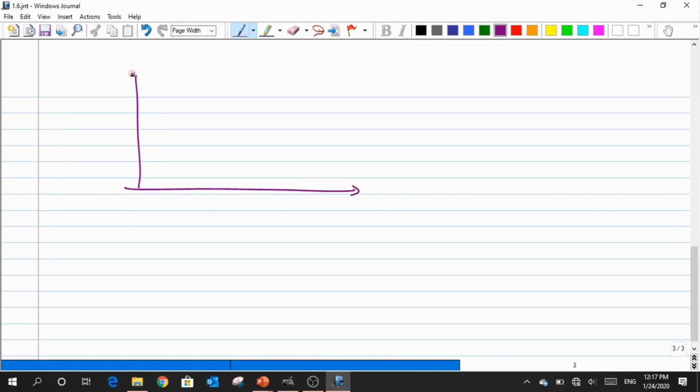So I'm just using the first quadrant, due to which I will write it as VSG2 and then ID2, and I'm just putting a modulus just to make sure that the PMOS currents are being plotted in the first quadrant. Clear? Now, how will I draw the graph of this?